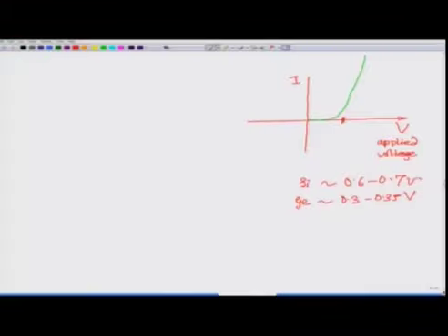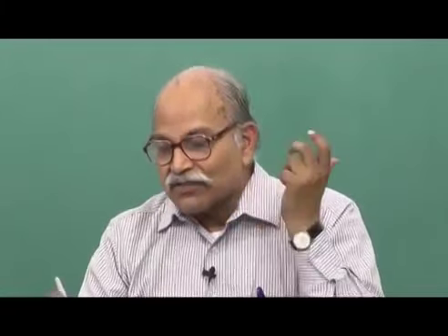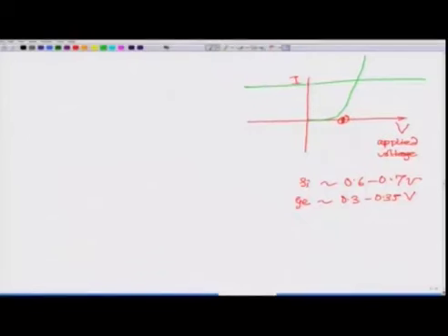So, if you are using this in a circuit, you have to put proper resistances, and the design should be such that after this voltage, when the current suddenly rises, the current should not become very large, and the total current in the circuit should remain less than the rated, allowed current, otherwise you will have a lot of heating and the whole characteristic of the semiconductor may get damaged. So, that is about the forward biasing.